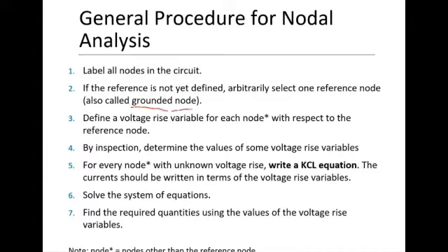So this works because we're looking at the potential at each node. Okay, and if we assume one to be a reference node, the potential difference between two nodes is not changed. So think of it as something like if you have some level here with a height h1, and some ground level, of course, with a height 0, and another level with a height h2.